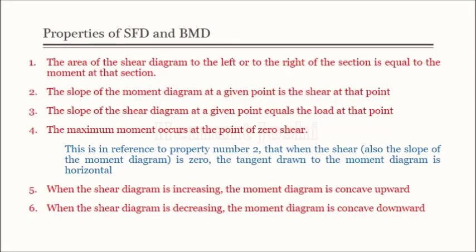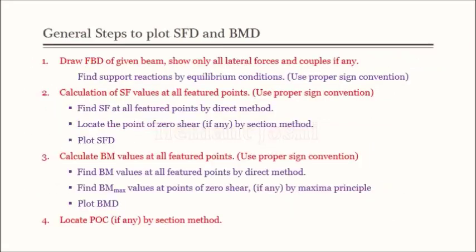Similarly, the maximum moment occurs at a point of zero shear, that already I have discussed, and when shear force diagram is increasing, or one can say when UDL is acting upward, then moment diagram is concave upward. This is simple nature we have discussed earlier.